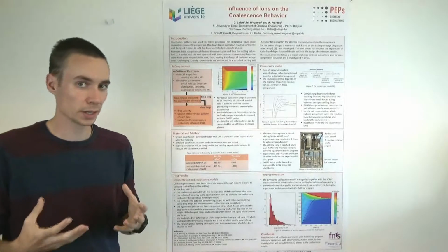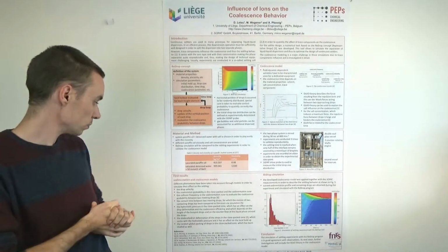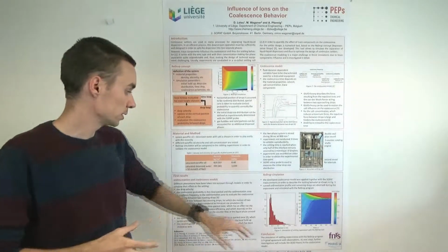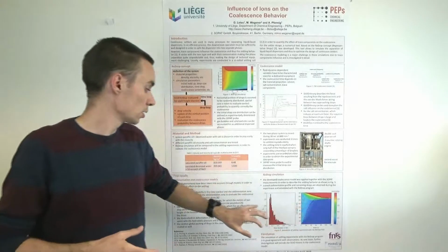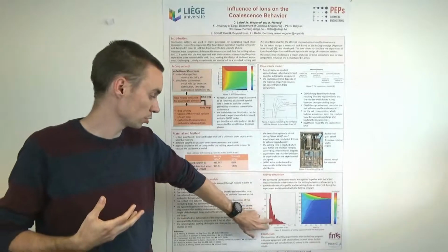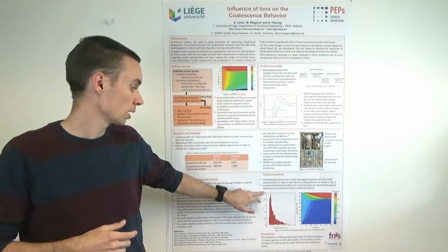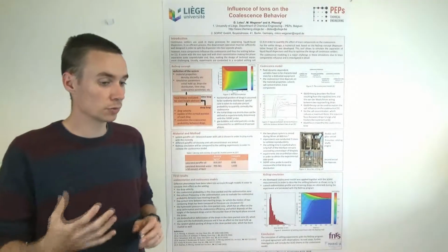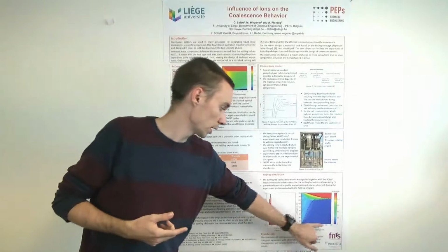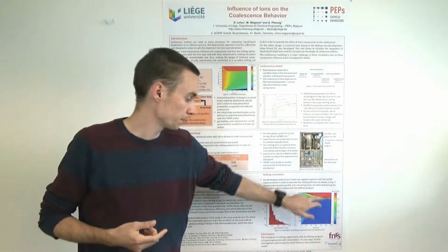I also studied the packing of a polydispersed system and compared that to the simulation. I also use a model for the collision frequency and for the contact time. And this is one of the results that I have. I do my settling experiment and measure the drop size distribution with the SOPAT probe, and I have this kind of graph. Here I presented the Q0. From the experiment, I also have the sedimentation and the coalescence curve, which is represented here. You have the height of the cell, you have the time, and the black dots here represent the sedimentation curve and the coalescence curve.